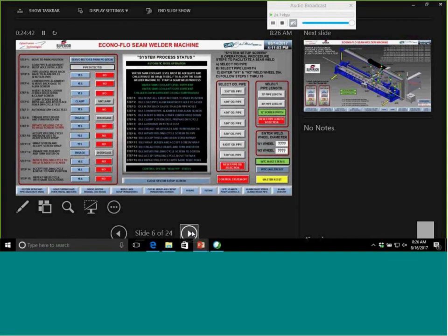And so when we actually weld the mesh screen to the pipe, we cannot be welding a mesh screen on the pipe at a hole location. Otherwise, it would bend through. So we have lasers that assist the operators on where to position the mesh screen onto the pipe. So that gives the auto alignment, if you will.